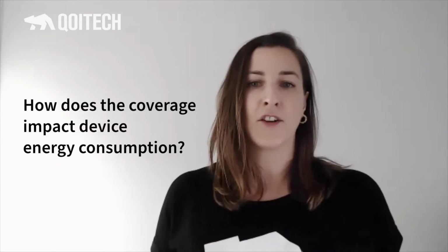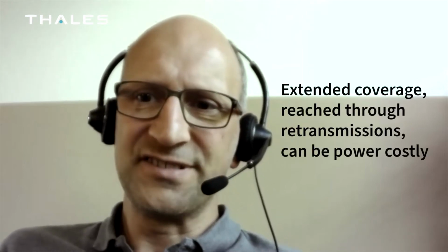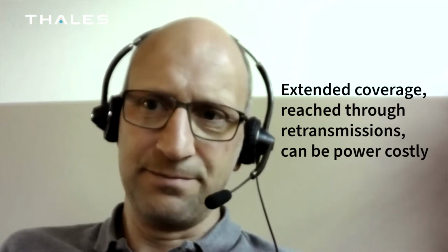How about the bicycle? Let's say, assume that it's actually out of the city, out of the coverage. NB-IoT and CAT-M offer an extended coverage anyway, where the device is doing retransmits of the data to get through these bad coverage scenarios. But depending on the protocol behind, retransmit may be confusing for the protocol, or maybe cause additional retransmissions, which finally cause more energy consumption.